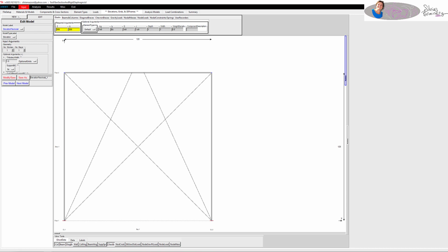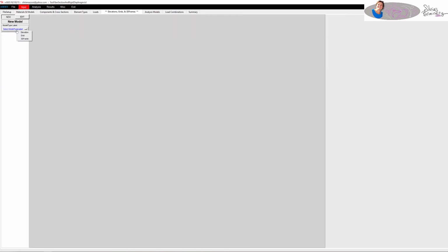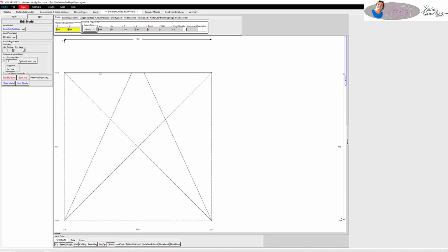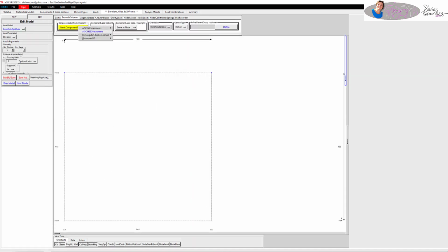So all the gravity loads and everything is saved. Now I'm going to build a new elevation that's just the beam, because I'm going to put these into a 3D portal frame. For the out of plane direction in the Z direction, I really just need to add a beam. To keep things simple, I'm going to have one beam using the PM interaction, and the other beam with no PM interaction.